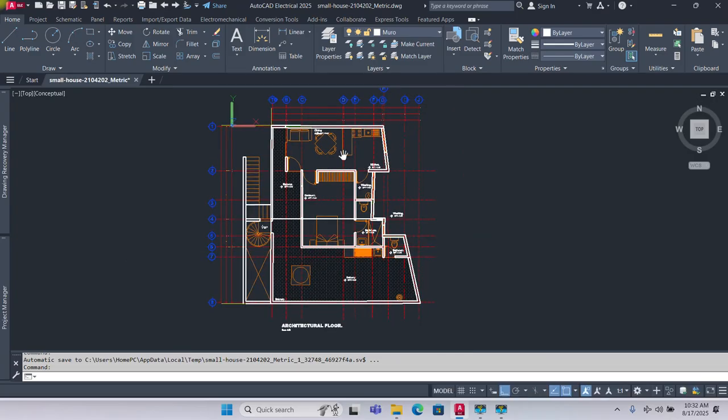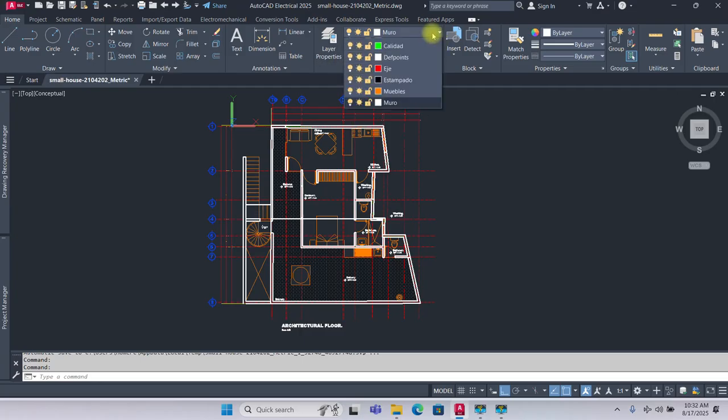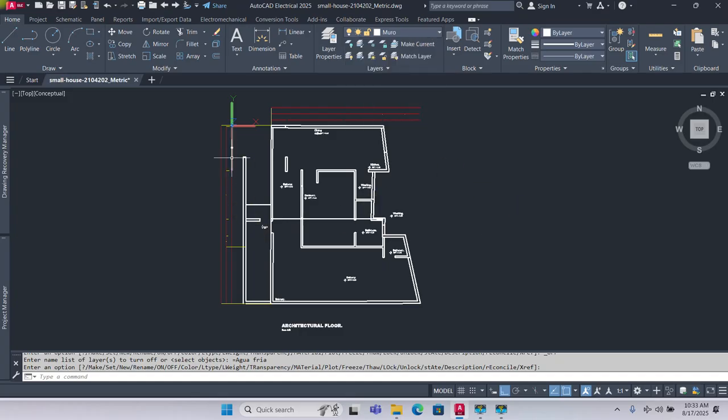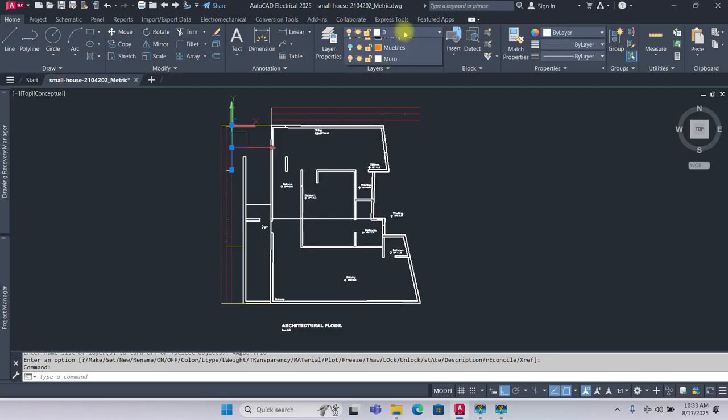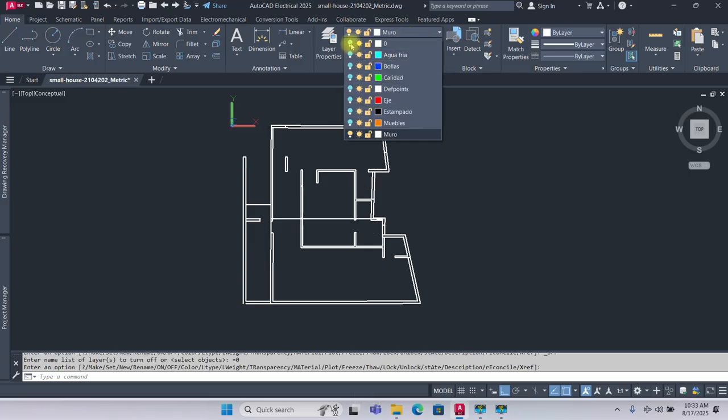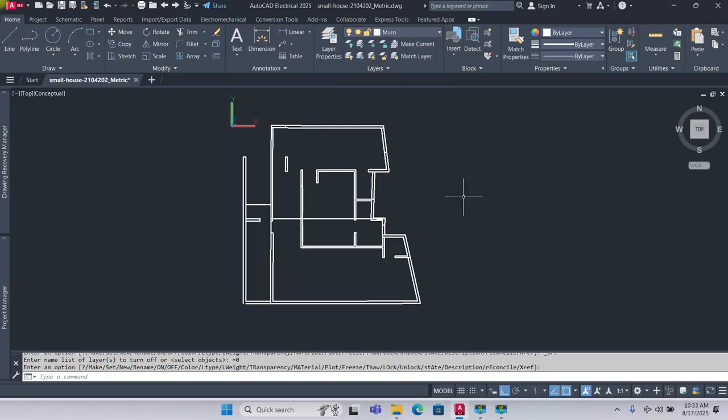The first thing I'm going to do is clear off things that I don't need in the scene. I only need the walls. That's where I want to start from. So I'll click on my layers and hide the layers that are not needed. I just need to leave this wall layer. This is in layer 0, and I've not turned off layer 0, so let me turn off layer 0 as well. So I just have this wall, and that's the first thing to do.